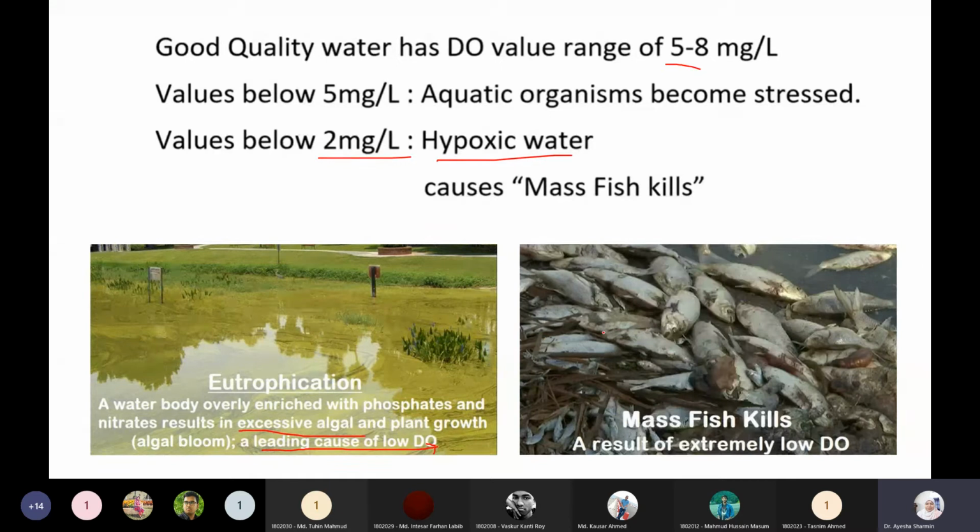So that's why you can see that monitoring the water quality with dissolved oxygen is so important. And these are because of the biological oxygen demand or biochemical oxygen demand. Sometimes what happens, you can also add some chemicals from the chemical industries going into the stream, and they also want to oxidize. So they will also take the dissolved oxygen and create the same kind of situation, and you'll see a lot of fish dying and coming out of the ponds.